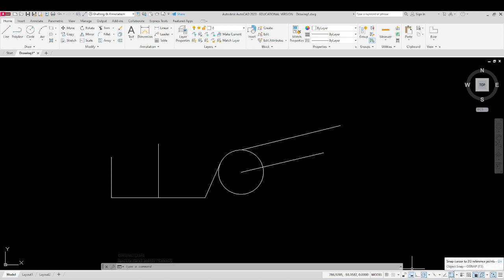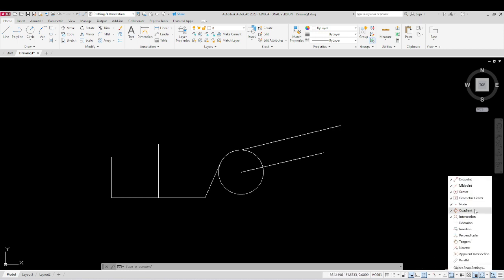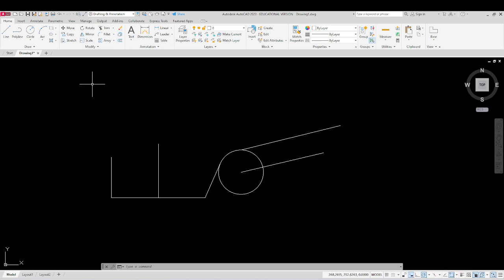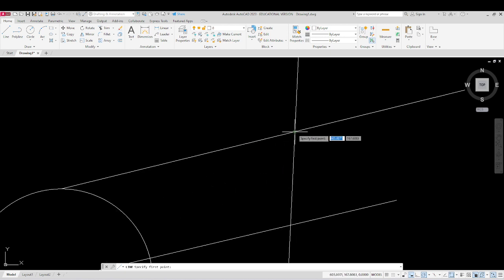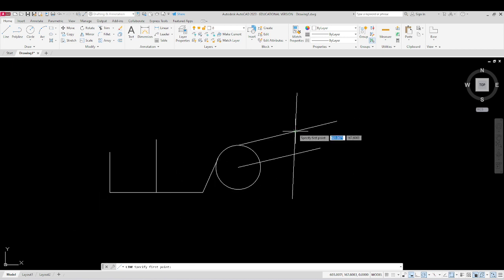Okay, I hope you have understood the things in detail. How the other object snaps will look, we'll understand in detail while drawing. But as of now, we'll understand some important object snaps over here. Okay, so you have understood about the center, end point, midpoint. If I draw a line crossing this line, and I go to the intersection part of it, I will get the intersection object snap, which is a cross symbol. Right? So we can select the intersection of any two objects.